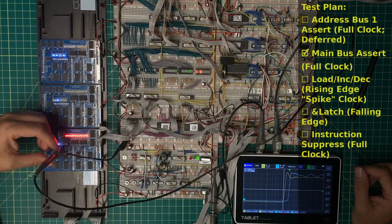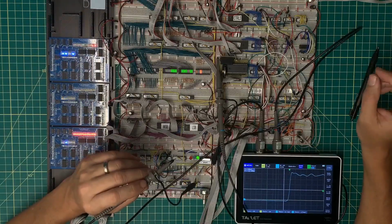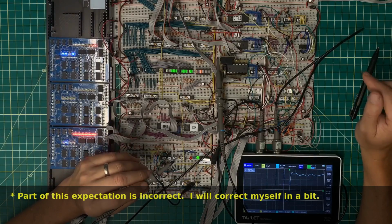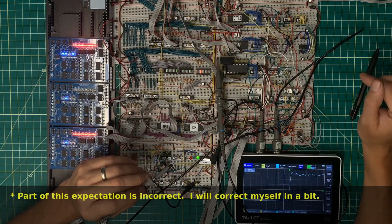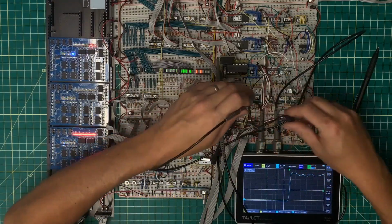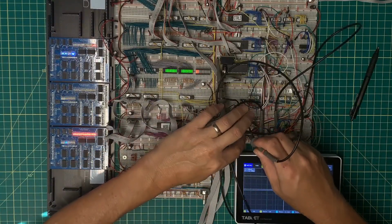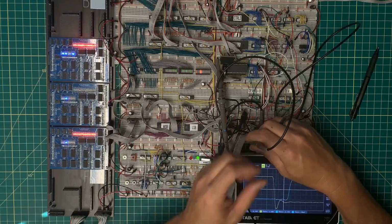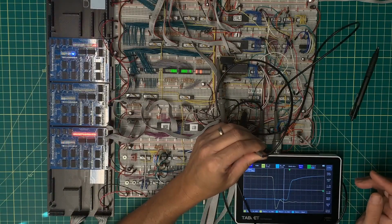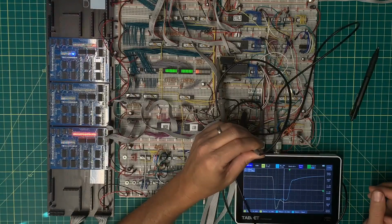All right, let me switch up and we'll take a look at the AND latch signal. Now, the AND latch signal, I am expecting to go high with the falling edge of the clock and then come back low again with the rising edge of the clock following that. So let's see if we can find a place to measure that. So this is R2, and we're measuring the rising edge on channel 2. And what I'm seeing is quite a significant delay here.